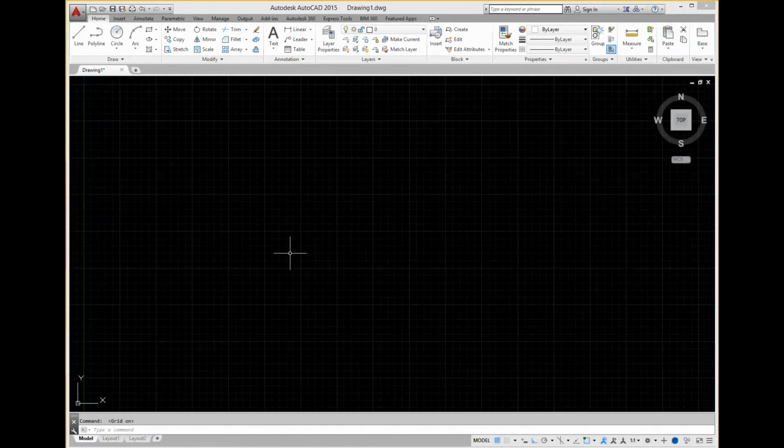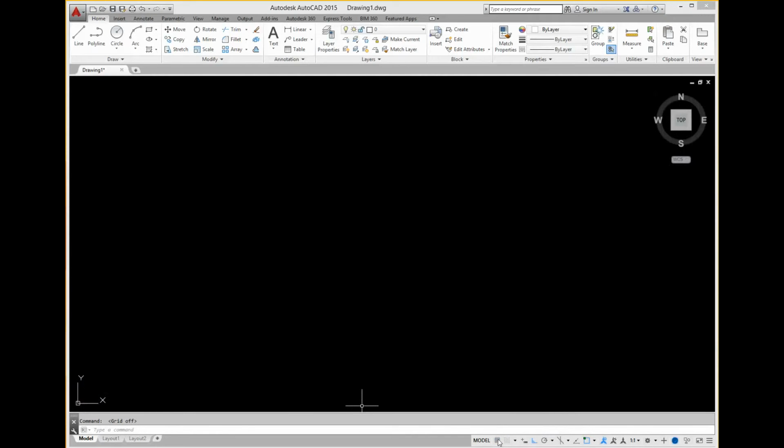When you first open AutoCAD, this is the screen that you see. You got the ribbon here at the top. Up here also at the top left is the undo button, which is very important to know about. We have this bar down at the bottom. If you click on the first button here, it should be the first for you, that'll turn the grids off and on. Come over and find the ortho and turn that on, and then come over and turn on the OSnap and turn everything else off.